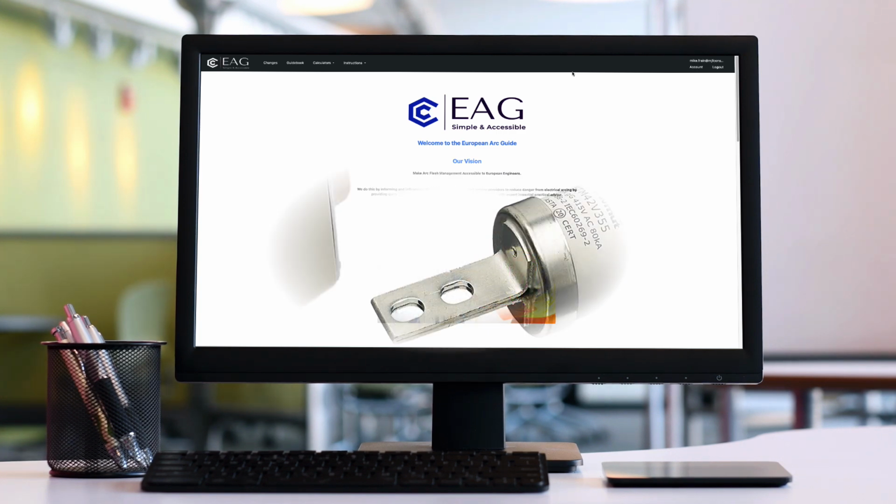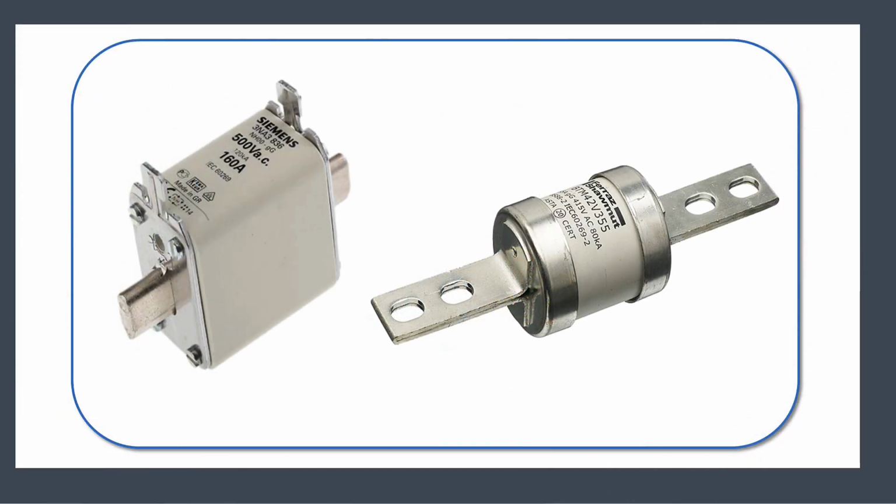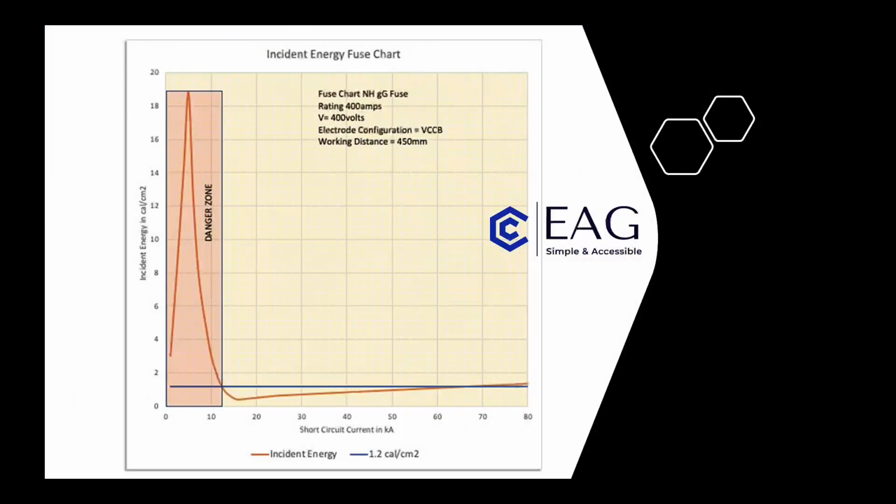The fuse charts give a very quick way of determining incident energy for 400 volts three-phase circuits that are fed by HRC fuses to the standard IEC 60269 that are commonly used in Europe. These types of fuses are extremely efficient at clearing very high fault currents rapidly and safely when operating in their current limiting zone, as shown here.